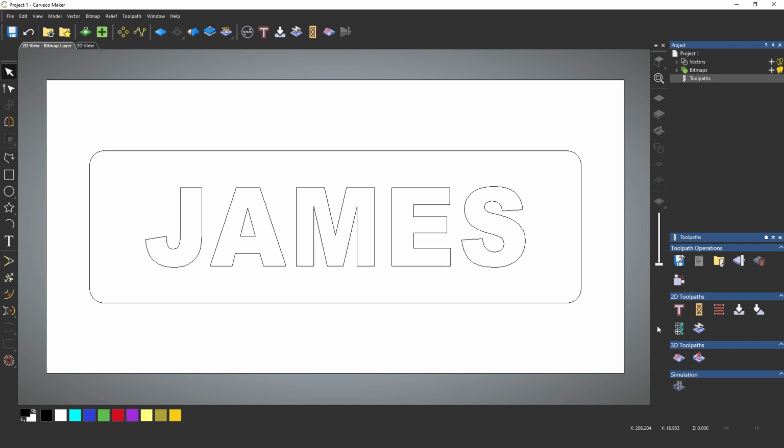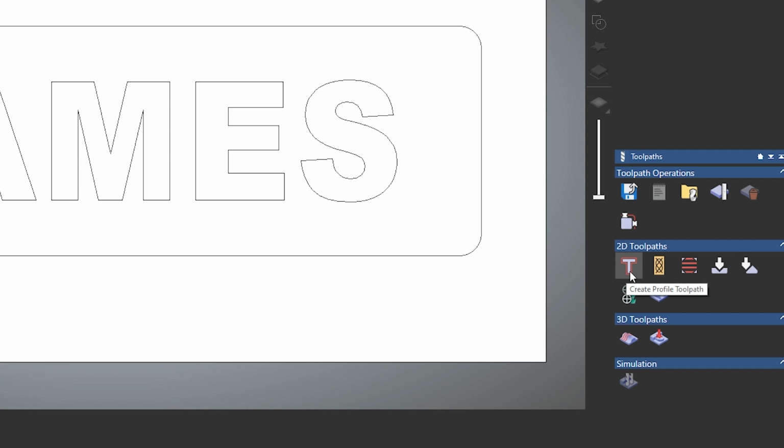We've got 4 or 5 up here, whereas we have about 8 going on down here. I say 8 because the second one under 3D is actually for laser machining, which we will ignore. So just as a reminder, if you hover over each tool, it will give you a description of what it does. We have profile, fluting, area clearance, V-carve, bevel, hole drilling, and inlay.